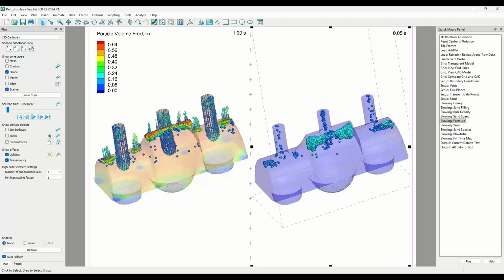Okay, let's see here. You showed cold box curing using blown sand. Can you also do this with inorganics? I think this is talking about the curing after blow. So is that available for inorganics as well, and other considerations there? Absolutely, that's a great question. We can do exactly the same thing. It's the same on the inorganic module.